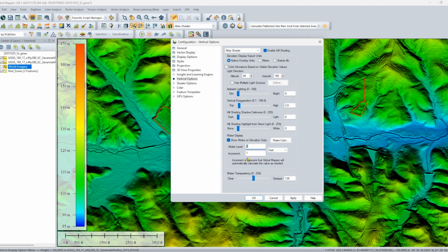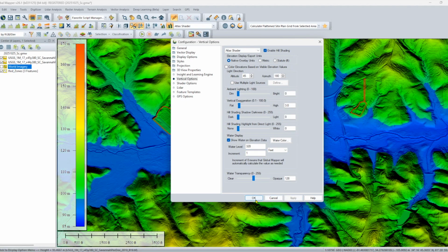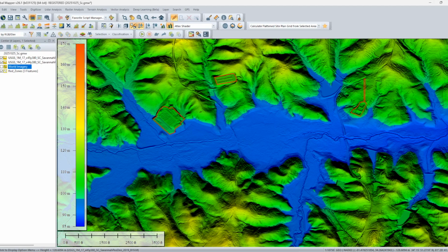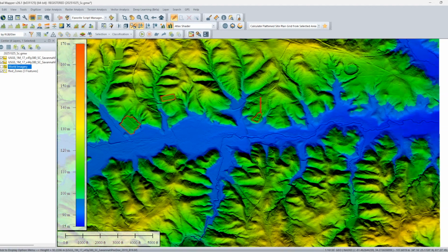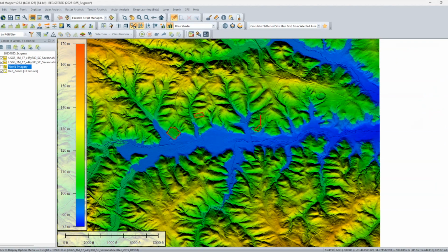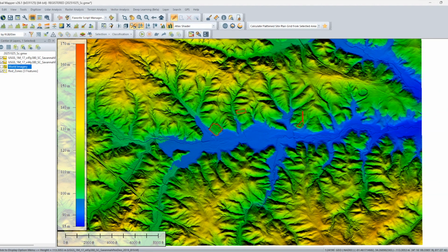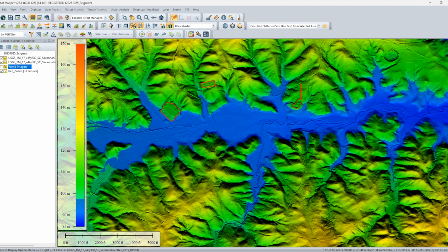All right, now all I've got to do here is enter an elevation value close to where I want the reservoir surface to be. I'm starting with 320 feet. That's roughly the same elevation as one of those red zone areas nearby. So it gives me a good reference point for how far the water might spread. As soon as I hit apply, you can see the terrain start to fill. This is where the model gets interesting, because you can visually test where the water line sits in real time.